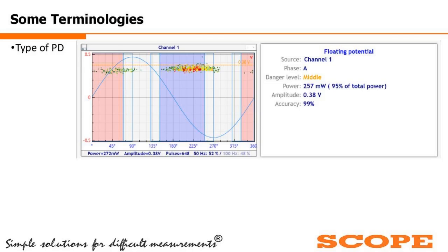Now, this is one thing your system should always be capable of: knowing the kind of partial discharge. People nowadays refer to a reference signal or reference noise: I require a reference noise for corona, I require reference noise for X, I require reference noise for Y. It sounds quite easy, but it is actually quite tough, because in a substation we have such a variety of equipment available. Every time, matching these figures with the standards is not that easy.